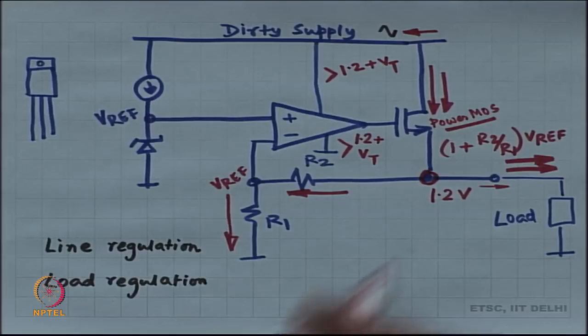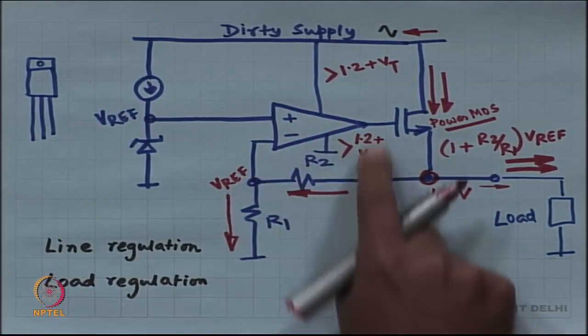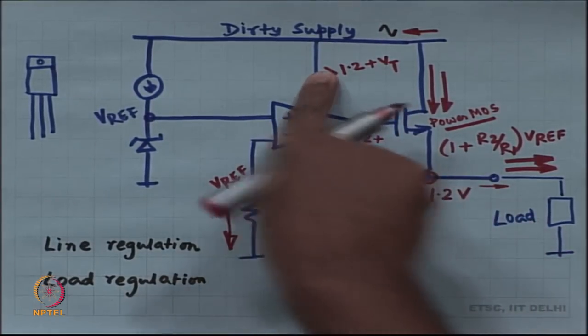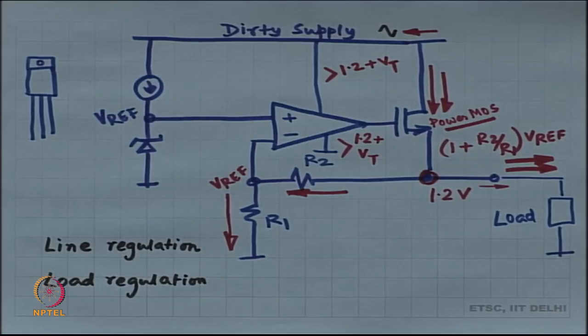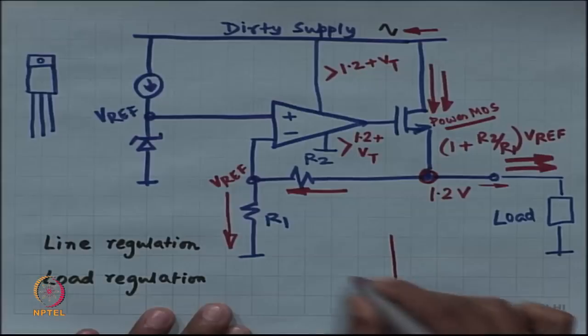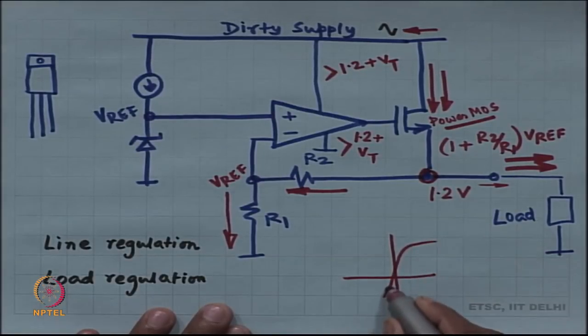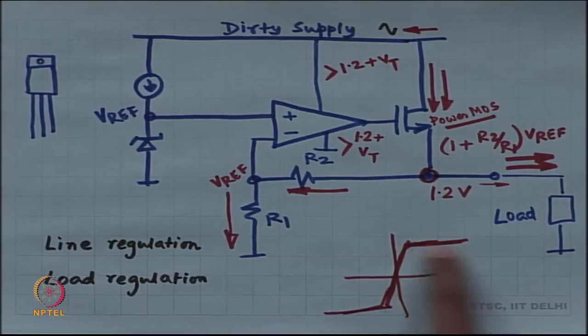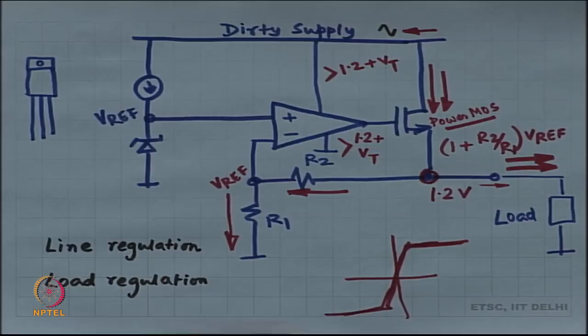and that is also a super optimistic situation, because if you want this op amp to be having any gain, then the output voltage of the op amp can't be equal to the supply. The output has to be lower than the supply. At the point where the output is equal to the supply, the op amp does not have any gain whatsoever. The gain has become 0. The characteristics of the op amp has become flat. So, the op amp characteristics, remember, we have discussed, it looks like this. You want to be in the high gain region of the op amp, not in this flat region of the op amp where there is no gain.